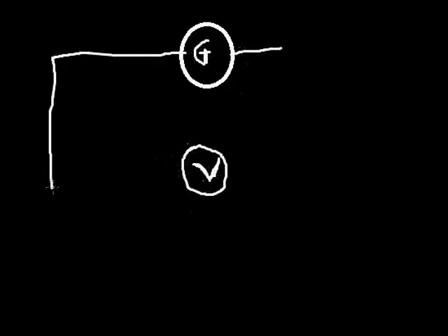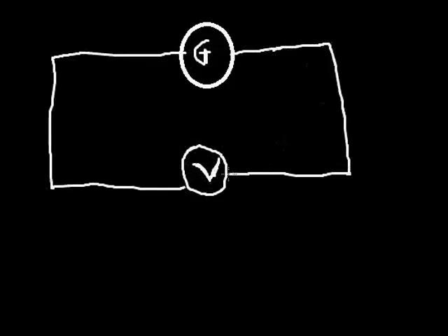So if I should actually apply the entire voltage of voltmeter, it will damage it. So what happened? I need to split the voltage. So for me to split the voltage, I will definitely have to connect a resistor in series. And this time around, the resistor I have to connect in series, we call it multiplier, Rm. So please take note. And of course, this is Rg.